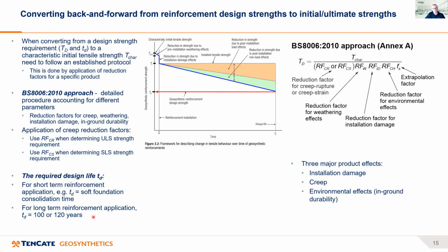But if, say, you had a long-term reinforcement application, for example, like a retaining wall or a reinforced slope, then the reinforcement design life may be a lot longer, up to 100, 120 years. Okay, so let's look at these three major factors in a little more detail.